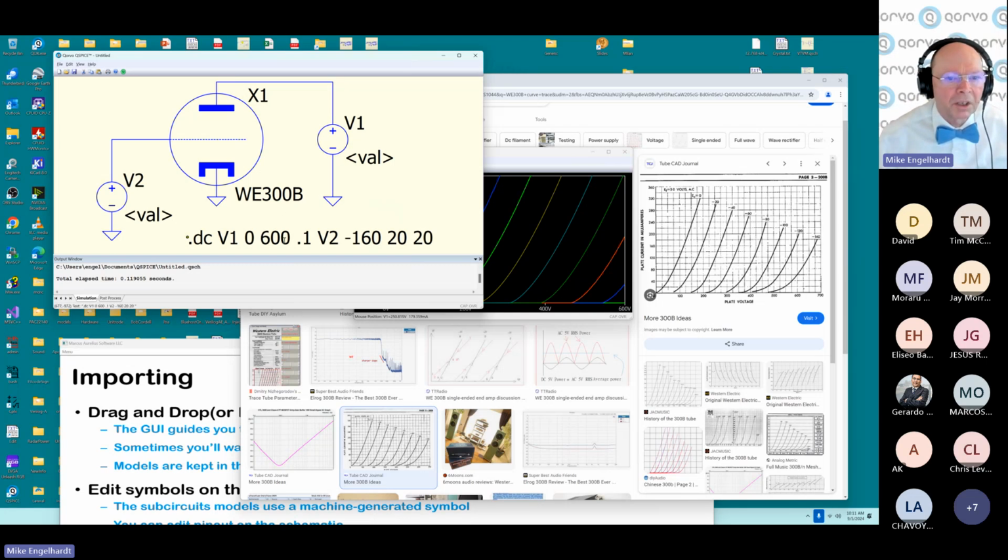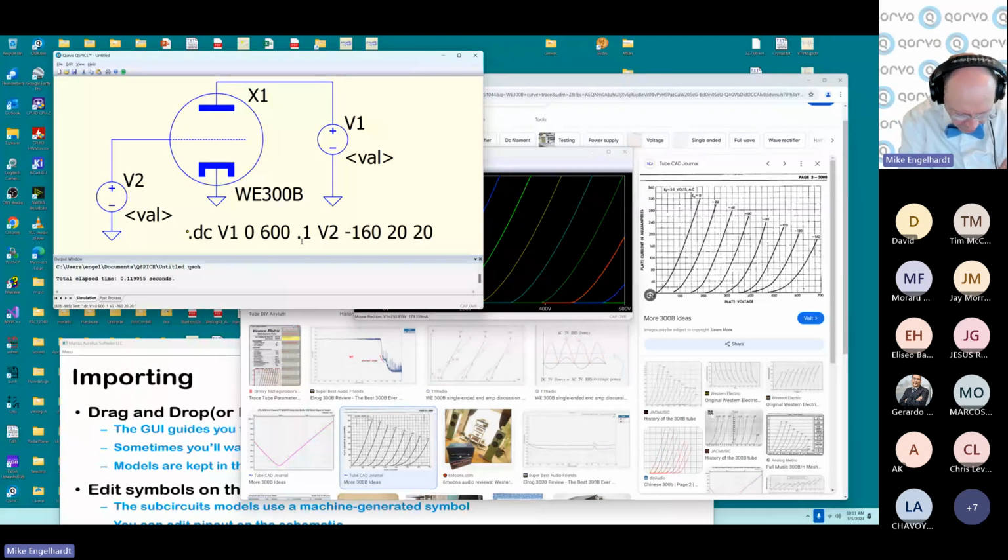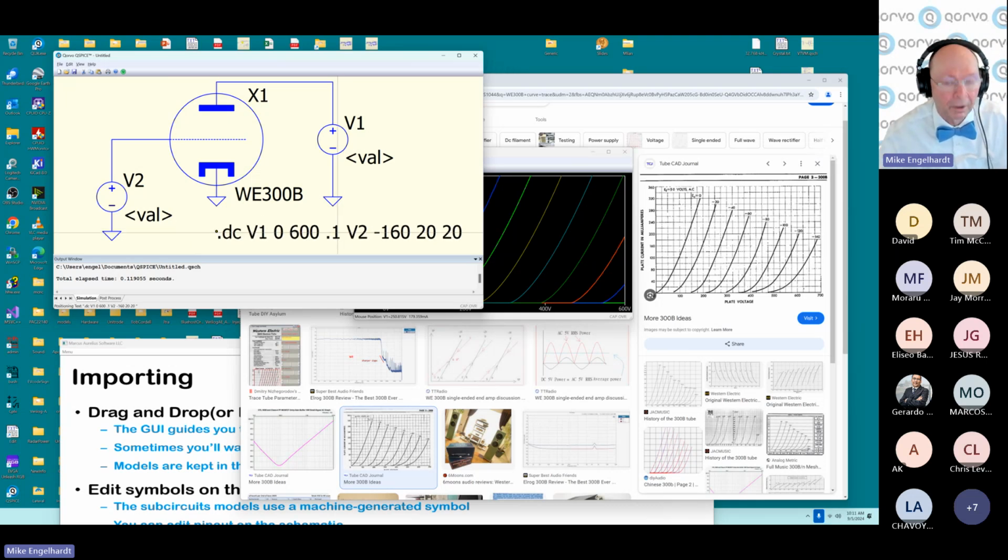If you put text, it's half a grid. But if you hold down the Control key, you have a finer resolution. There are three modifiers: you can press down Alt, Control, and Shift. It doesn't matter which you press, but the more of them you press down, the finer the grid size you get, because 1/100th of a wire grid is a very fine grid, and normally you don't want that.